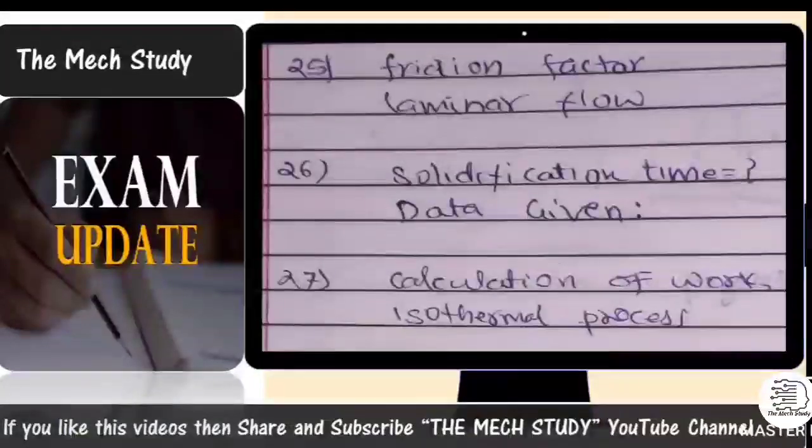Going with the next one, you need to come up with casting. They will ask two questions. One question is directly from the top gating system, bottom gating system relation, and one question is basically from calculation of time. So they will provide the constant and basic details like diameter. You need to calculate the solidification time in relation to another. If you have two systems, they have compared data first and second, so you do not need to find the constant K or C. Basically you divide the ratio and solve that type of question as well.